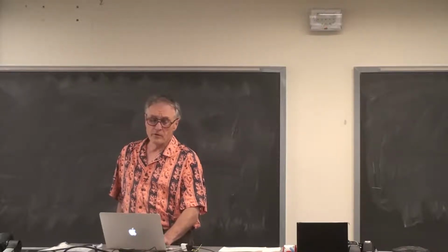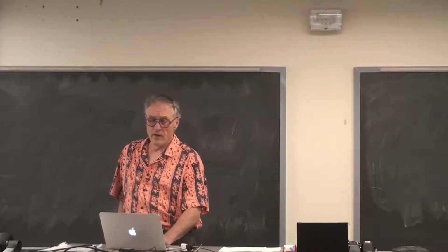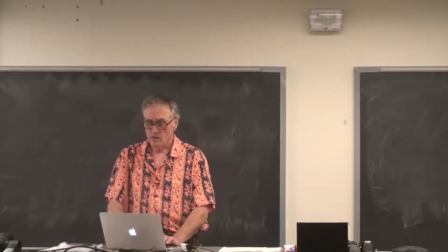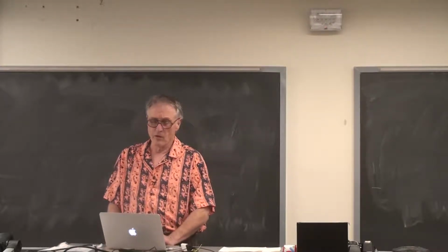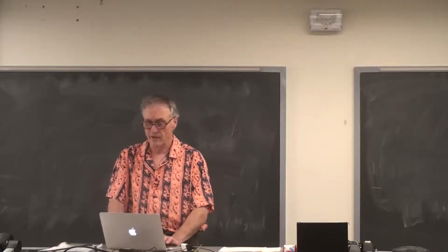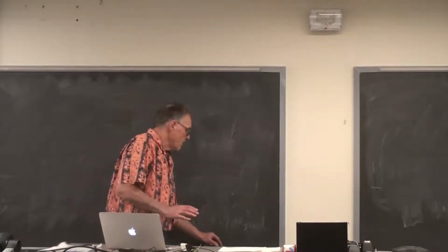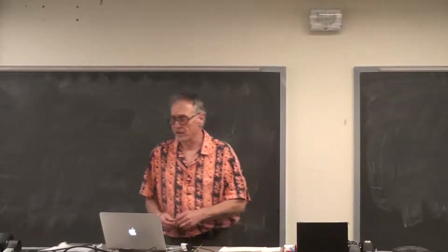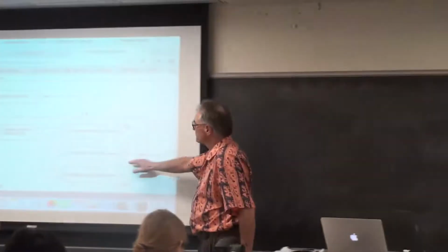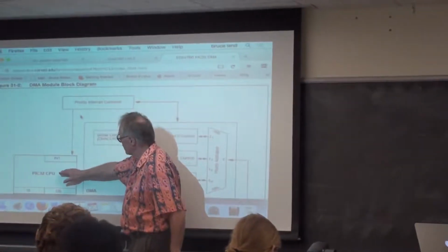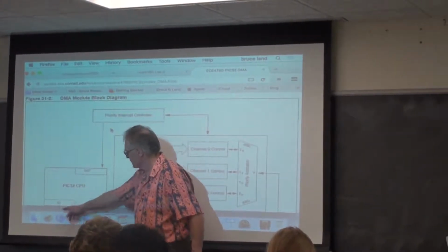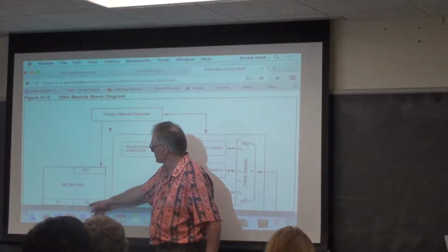The first thing we need to do is talk more about what direct memory access is, and then start talking about the effect of DMA in this lab. A DMA controller is a device which is a bus master. So the PIC32 is over here. There's the PIC CPU over here. There's an instruction master and a data master.